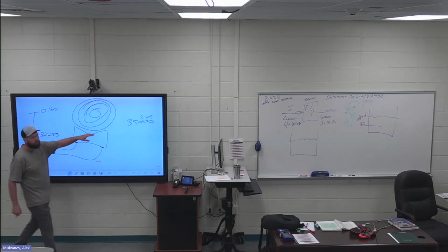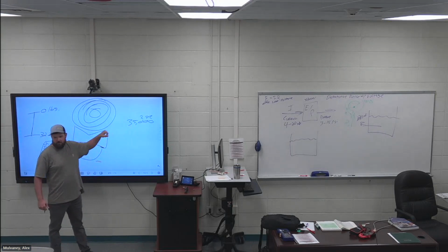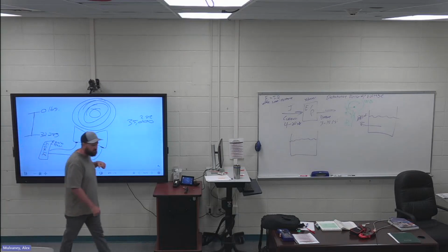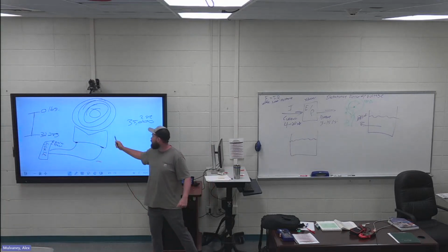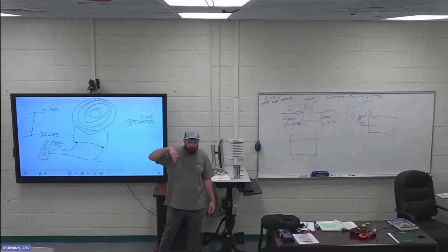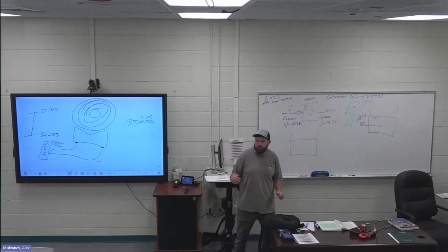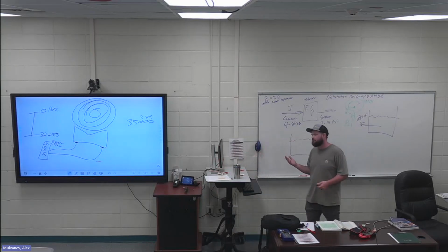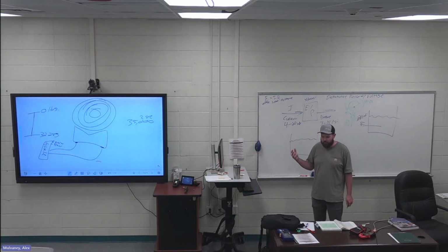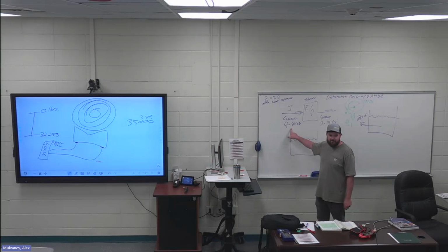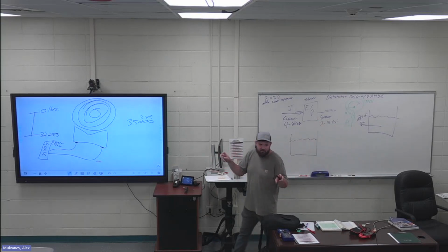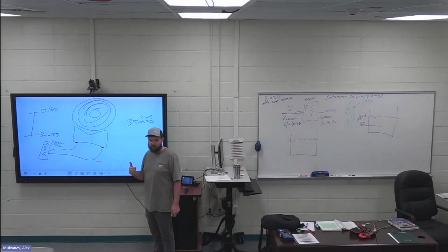There's no coil I'm going to put on this scale that's going to be heavier than this, and no coil that's going to be lighter than 0, right? So that's calibration. Your known value is whatever you're putting on that scale. You can also do this with different pieces of meters, where something might get a 4 to 20 milliamp signal. We have process meters that can go from 4 to 20 milliamps and output that and simulate a signal, but it's a known signal.